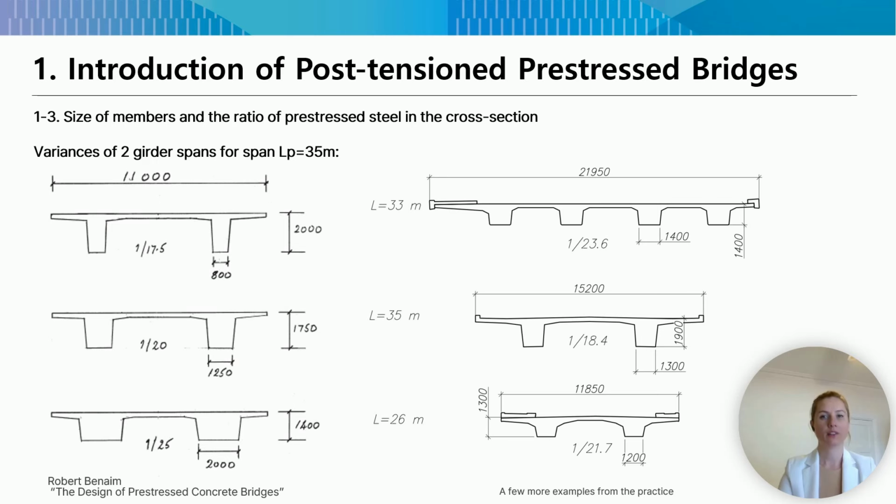Considering the characteristics of this type of superstructure, the following can be noted. The designer's task is to find the optimum height and width of the rib. As shown on the previous slide, the stresses counteracting external loads depend on the position of the pre-stressing force at the height of the section. In other words, on the height of the beam. While reducing the height, the width will increase to provide sufficient ultimate strength. As a rule, the bending moment at the supports is the governing criterion.